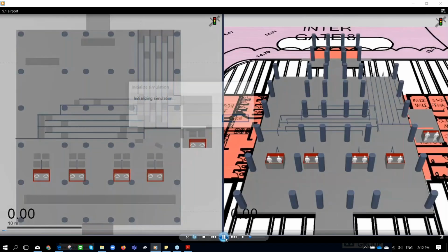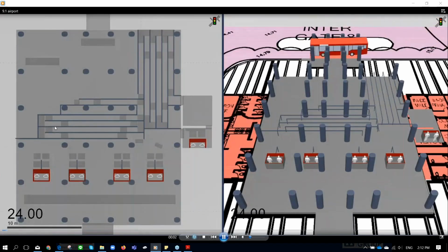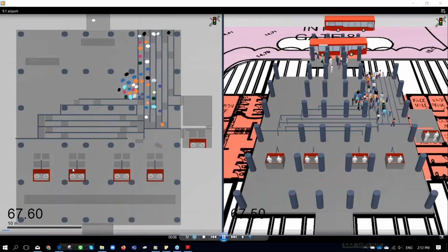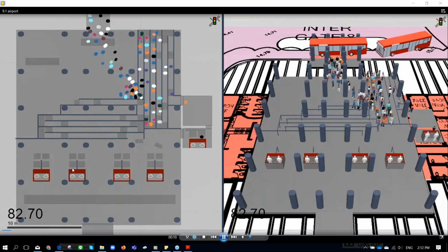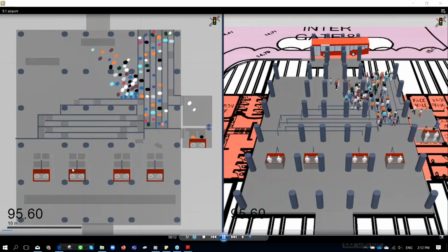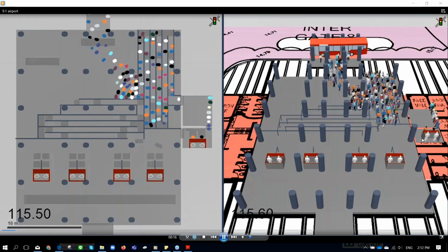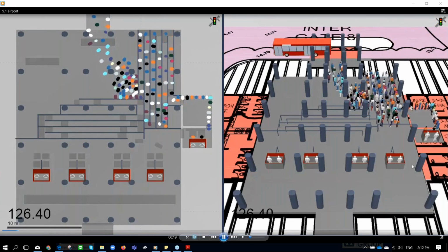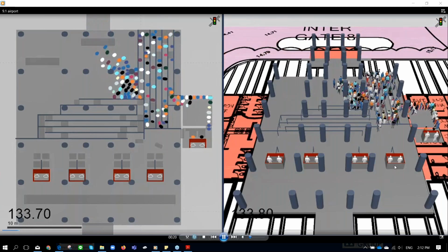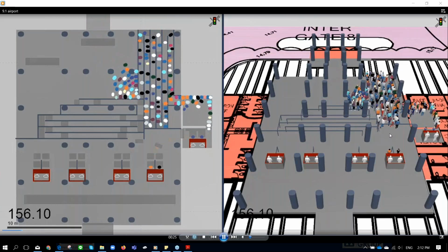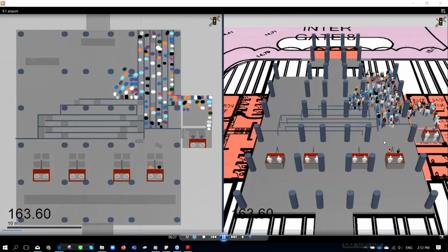Okay, let's talk about pedestrian simulation, not for normal operation, not for evacuation. This one is an example of an airport. During the design process, the designer said that two booths of immigration would be enough, but we rechecked and confirmed that no, it's not enough for normal operation.